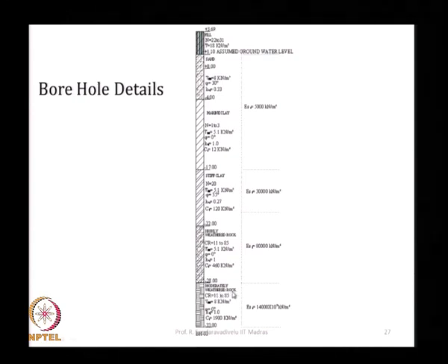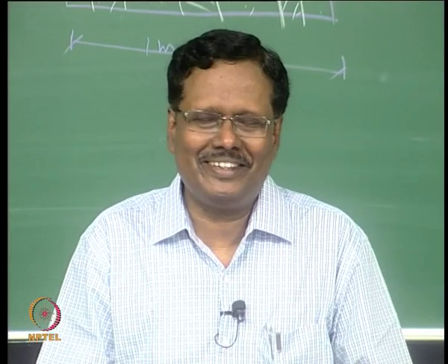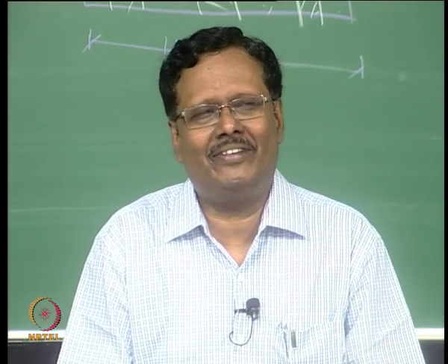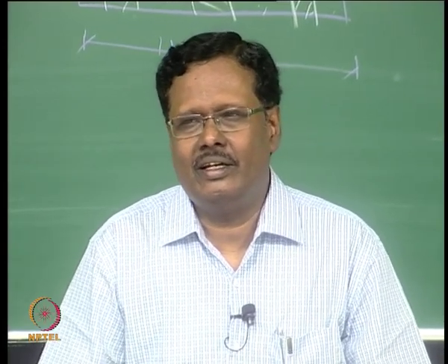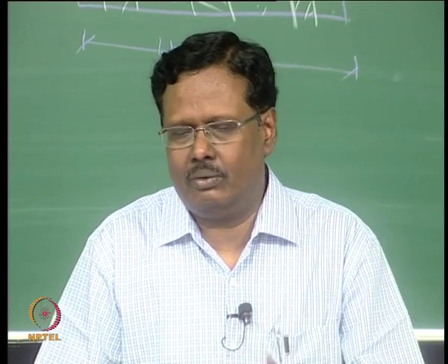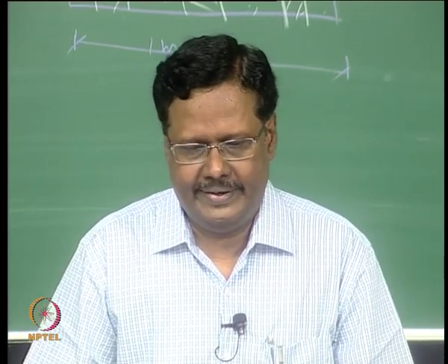Similarly it is moderately weathered rock. Which is a better rock, highly weathered rock or moderately weathered rock? Moderately weathered rock is a better rock. Do not say highly means it is good. Highly weathered means the weathering action is so much that the quality of the rock deteriorates.